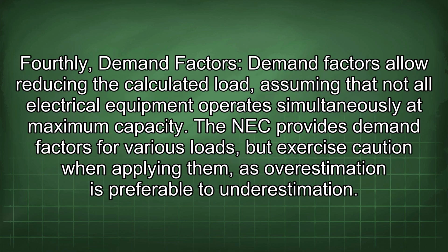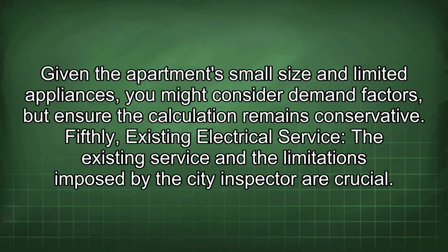Fourthly, demand factors. Demand factors allow reducing the calculated load, assuming that not all electrical equipment operates simultaneously at maximum capacity. The NEC provides demand factors for various loads, but exercise caution when applying them, as overestimation is preferable to underestimation. Given the apartment's small size and limited appliances, you might consider demand factors, but ensure the calculation remains conservative.